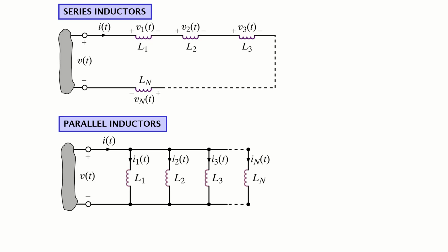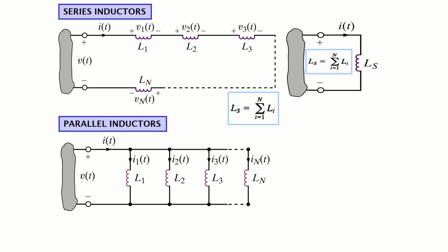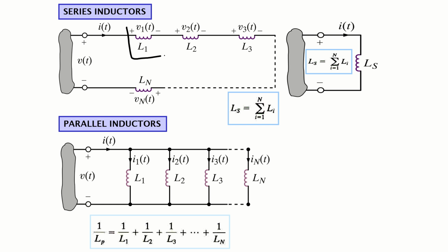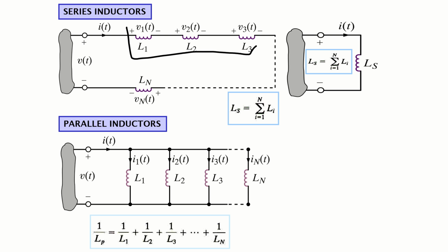Welcome back. So we have learned about the equivalent capacitance. Now let's have a look at the inductance. The inductance calculations are very easy, and the same approach as for a resistive network is applied. What does this mean? If we have inductors in series, you just add them together, like we typically do for the resistive network. To find the net inductance, it will be basically L1 plus L2 plus L3.